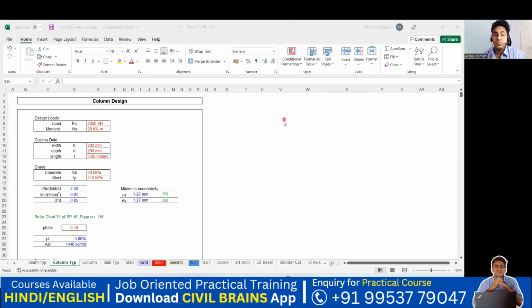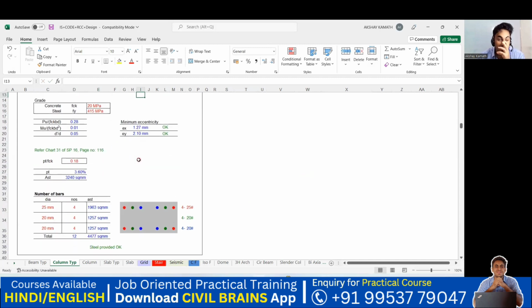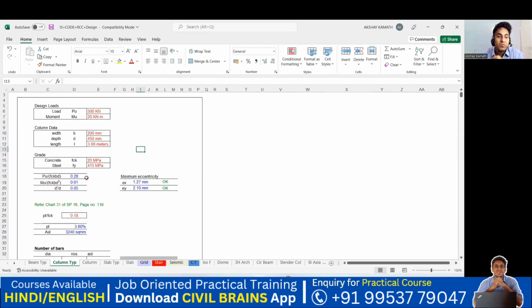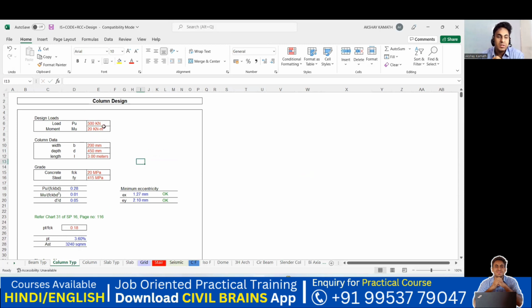Hello, my dear students. Welcome back to the lecture. So we'll see how the column design will be done. Let us say there's one column and the load coming on the column is 500 kilonewton, and the column size is 200 in width and 450 in depth. I'm going to get the steel required for this particular column of 500 kilonewton, having a size of 200 by 450.